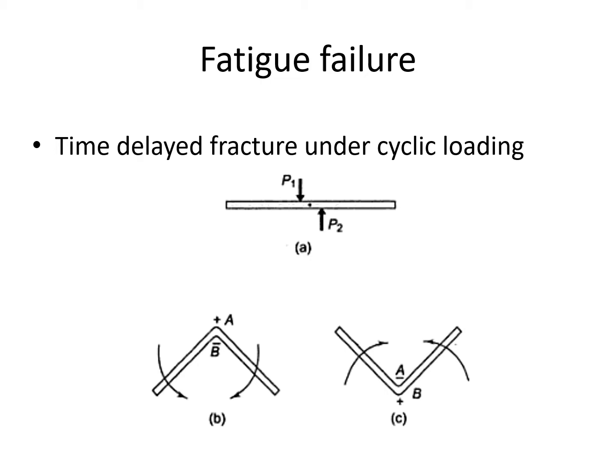Fatigue failure. Time delayed fracture under cyclic loading is called fatigue failure. This cyclic loading actually reduces our strength. You can consider a stick. If you are pulling and trying to break it, it may be difficult, but after bending it a few times, you can break it easily.